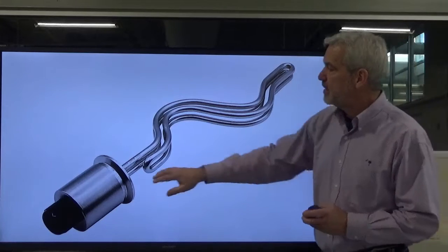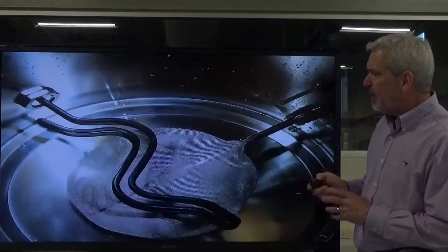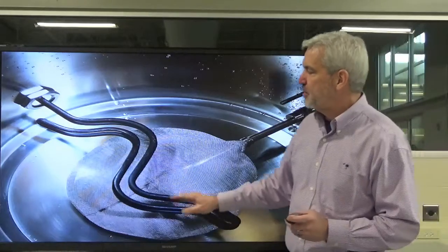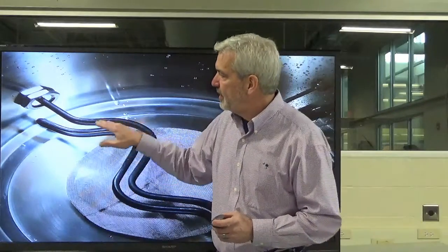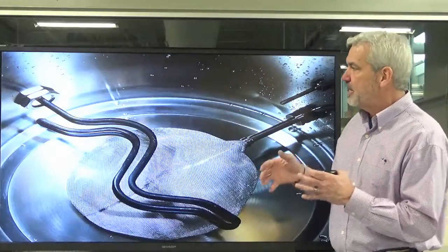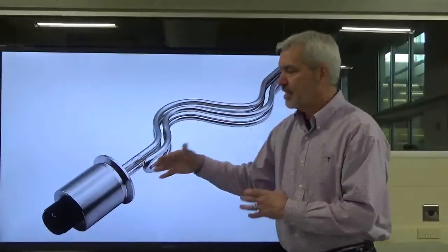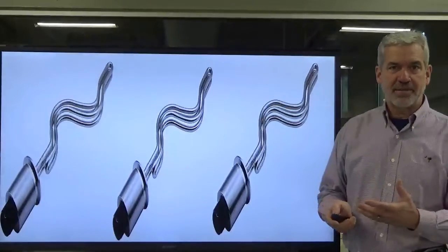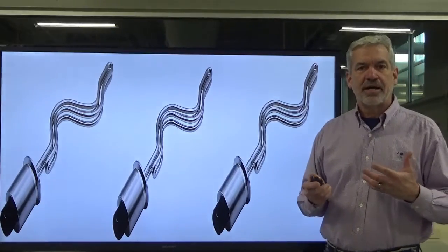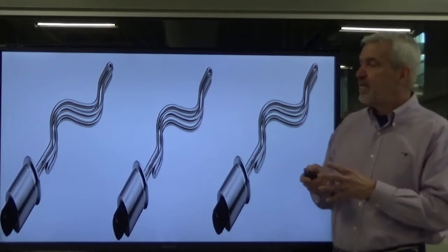Now, this is typically what one of the elements looks like in that boil kettle, okay? If you can see, this is a simplified version. Here's one in a tun here, boil kettle. And what it is, you stick it from the inside out, and there's a seal right there to keep the liquid from running out of the side of the vessel, obviously. But it's a seal there. It's got an electrical plug on it right here, so the wall of the vessel will be right here, so it's separated. But they've got 3 of these elements in that boil kettle, okay? And it really depends on what size of the kettle it is, the vessel it is, that determines how many elements you have. But in this particular case, they had 3 elements, okay?